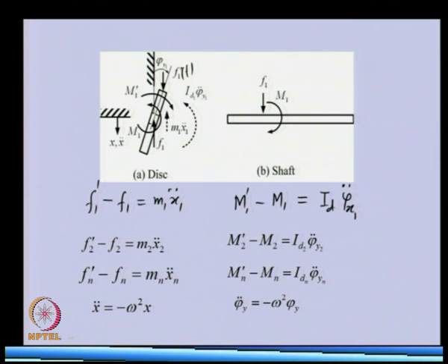So, this is Id1, here Id2, and we can extend this for the nth disk like this, where Mn is the mass of the nth disk, and Idn will be the diametral mass moment of inertia of the nth disk. These are all diametral mass moments of inertia, and this is the angular displacement and its time derivative, so the angular acceleration of the nth disk.